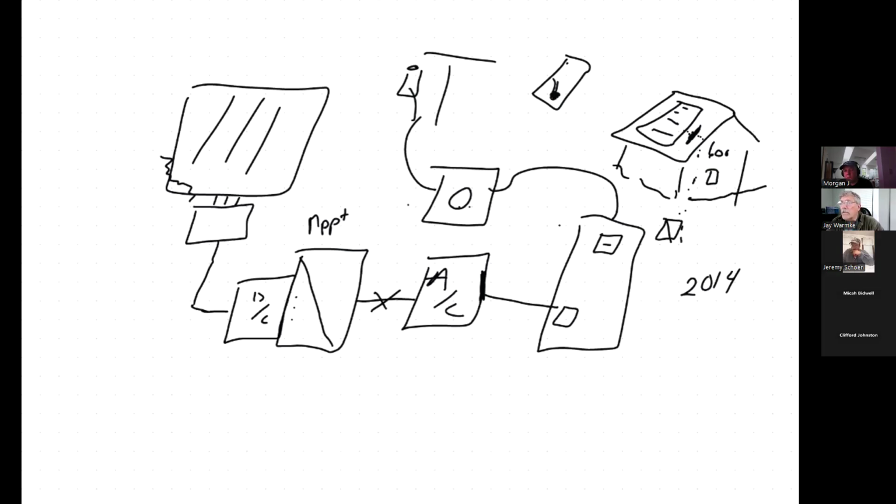All of this was in response to the rapid shutdown provision saying we need it to turn off at the panel. Well, it turned out that this was a good solution. And today, about 90% of all residential systems are either going to use microinverters or power optimizers. So it's just a better solution at small scale, at residential scale.